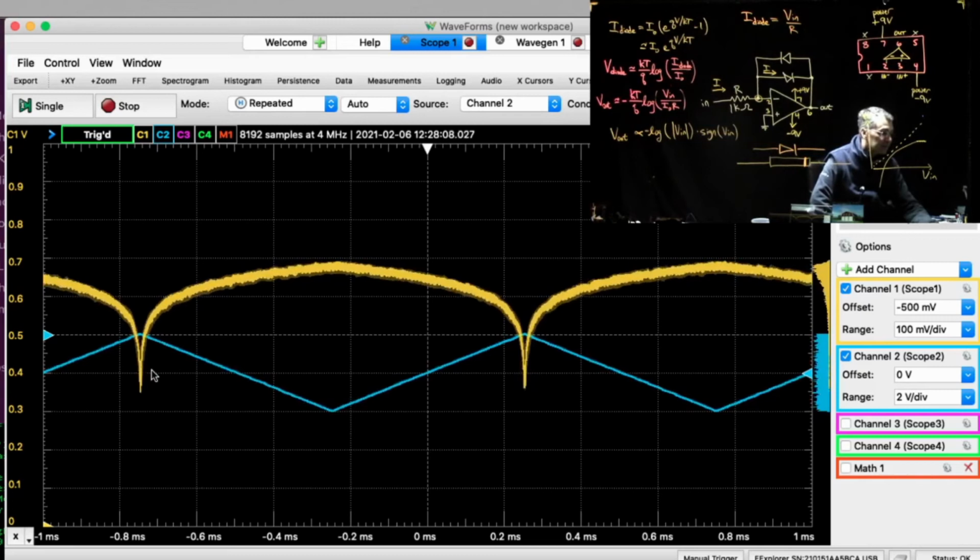So here you can see that a relatively small change in current corresponds to a pretty big change in voltage across the diode for this section down here where it's just barely turning on, right? So we're kind of like 0.3, 0.4, 0.5, 0.6 volts across the diode.